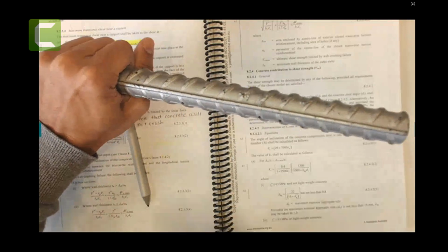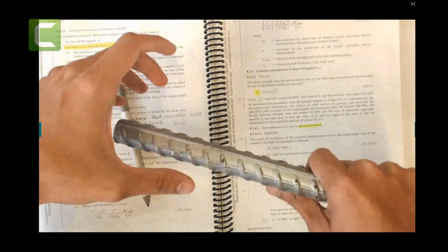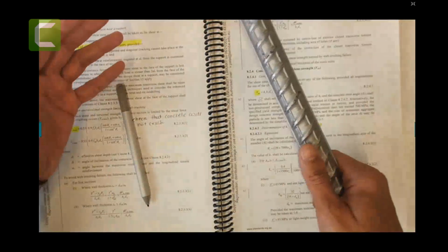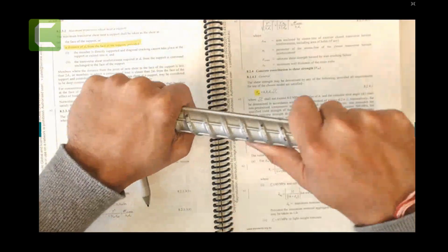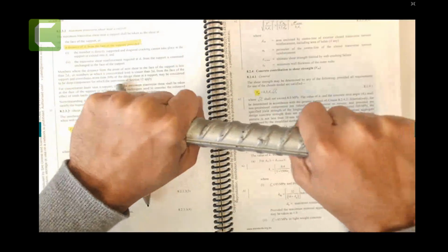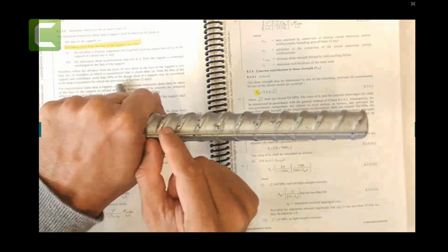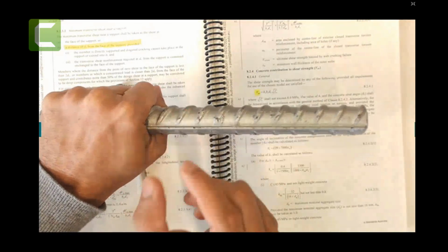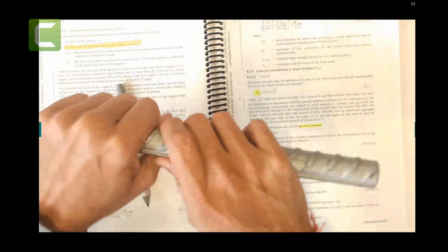So again, I can explain here. Hold it, not enough development length, bang, it comes out, no yielding, nothing else, no load carrying, and your concrete will just go into catastrophic failure. No ductility. With enough holding and enough concrete, you can't pull it out. You can look at that. You can't pull it, right? With enough development length, the load will try to pull this bar, this one is holding it, then the bar is going to yield and stretch until it reaches the yielding point. So there is enough ductility. It will give you enough warning before it fails.